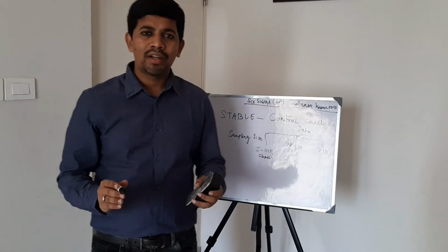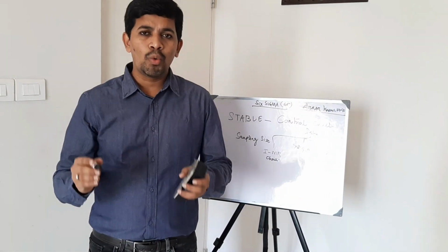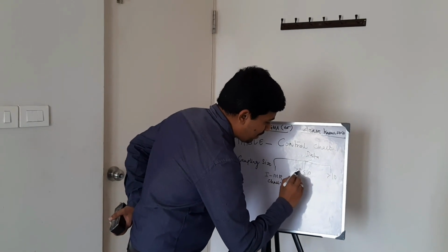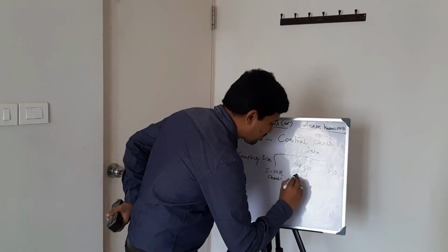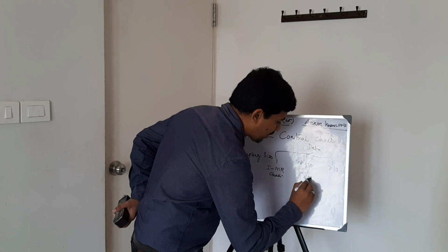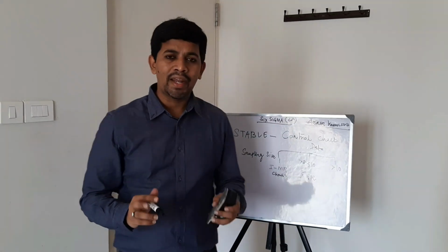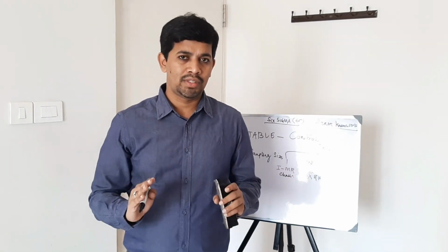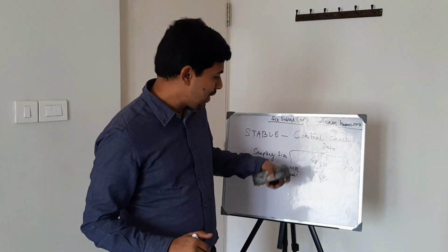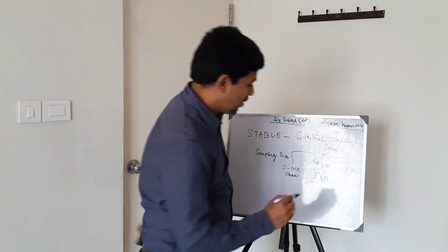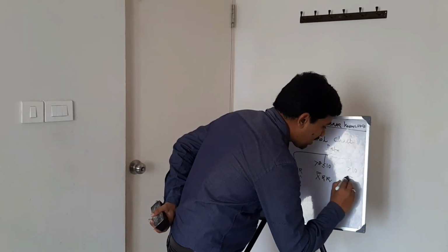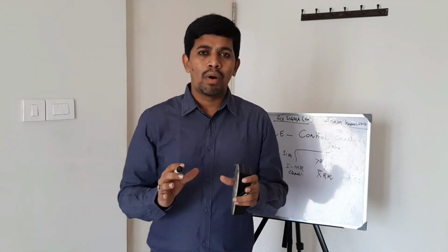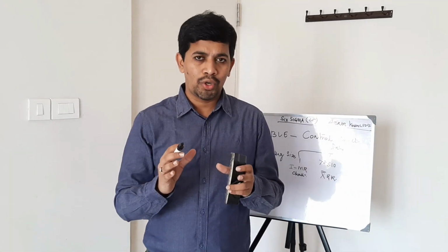The IMR chart, as you all know, is the individual moving range chart. If your sampling data is between this range, you can use the X bar R chart. X double bar means the grand average of a process. If your sampling size is greater than 10, then you can use the X double bar and S chart. So it all depends upon the data you have.